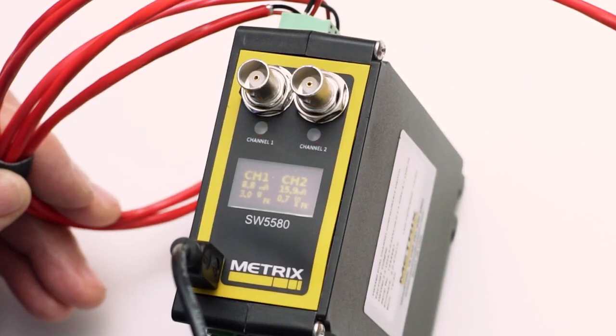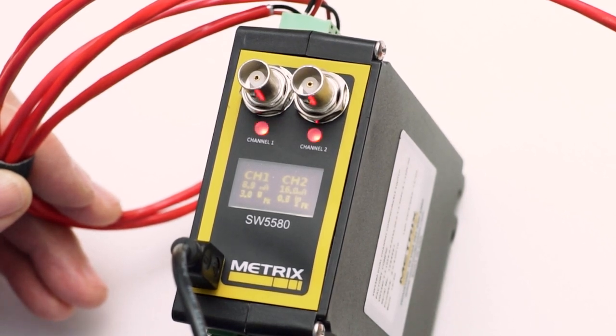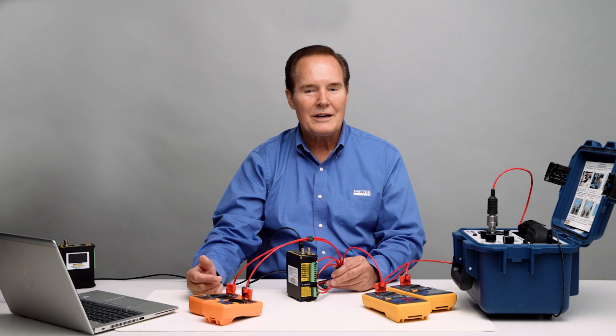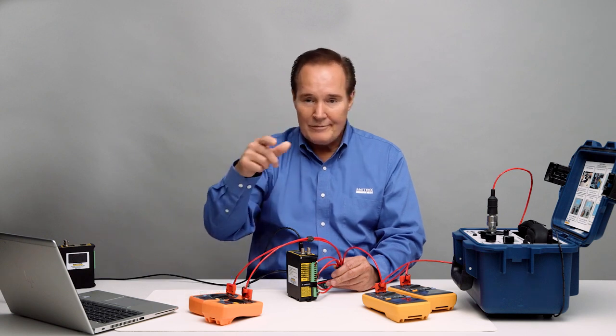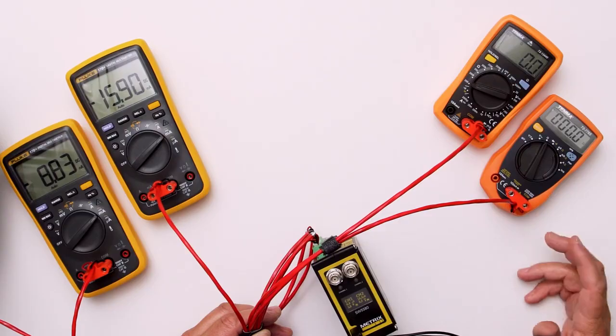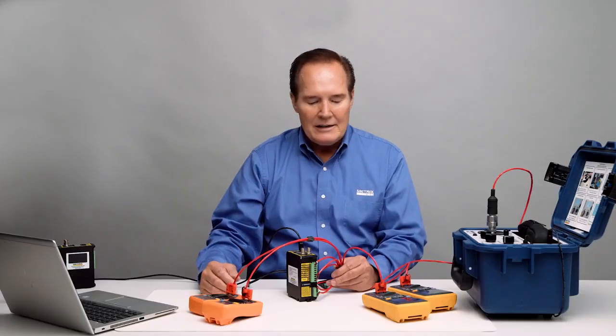Go to 3.2. Three seconds later, you see flashing red, and you can see we're close to a short. Okay, that's when the relay's shut. Just a short circuit now that the relay went on. And that's what you want to have. You want reliable relays that change state when you've set them per the time delay.